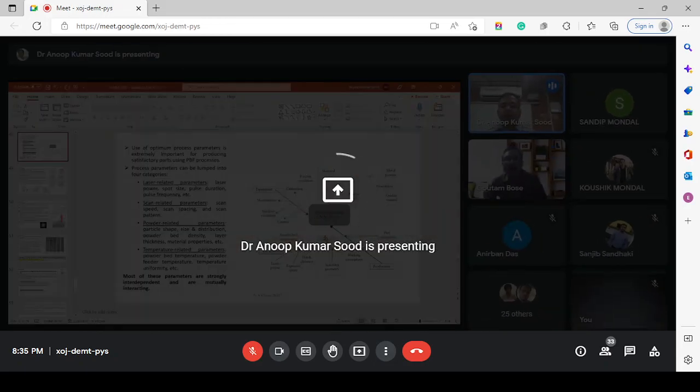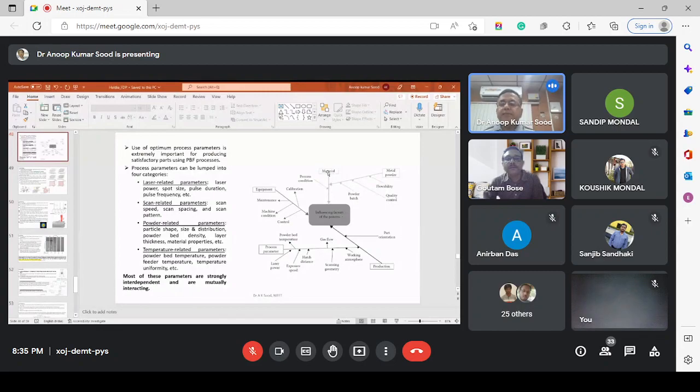Now, one of them is the material-related process parameter. I am just giving you one example. Others are also responsible for anisotropic properties in the structure, but one you can consider is the material layer. Like, I am using a powder. Now it is not possible that for every layer of powder I deposit, I get the same powder density and the similar powder configuration.